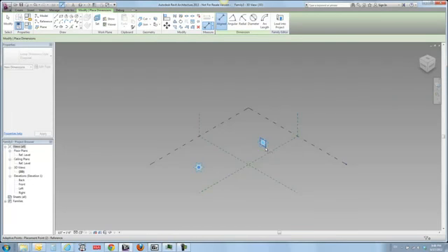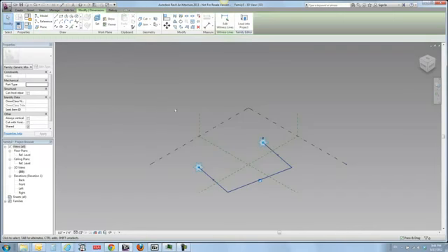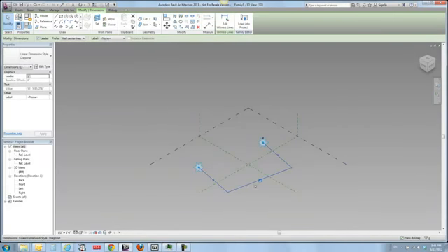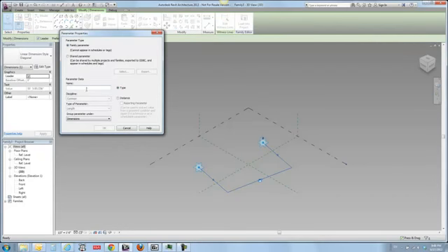I don't want to go to the reference plane, this is a reference plane. I want the actual point, because that will give me a measurement that can actually drive other pieces of geometry. So if I select that dimension, I can now name it, and once you name something, you have power over it. So let's call this distance. Now let's just call it dist.